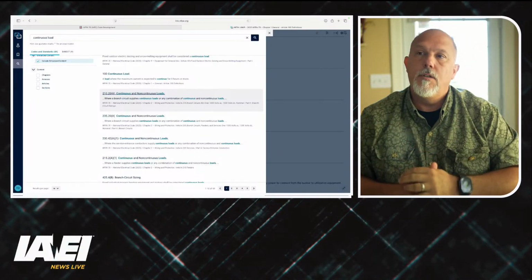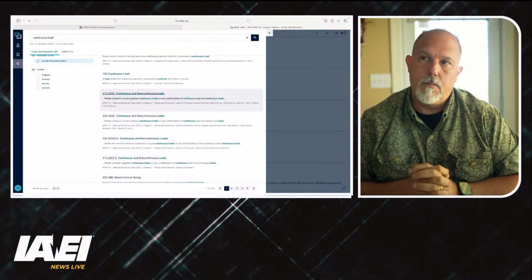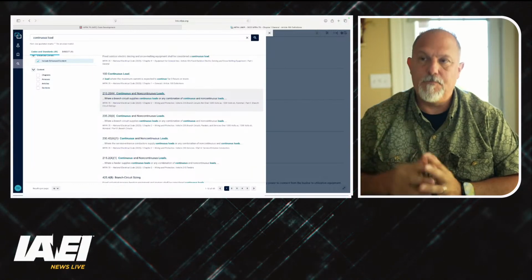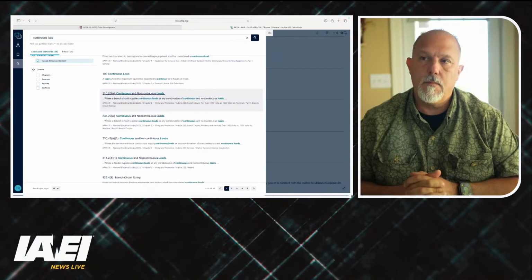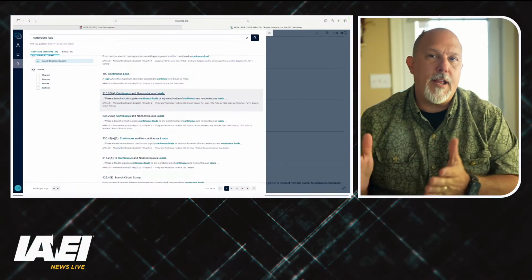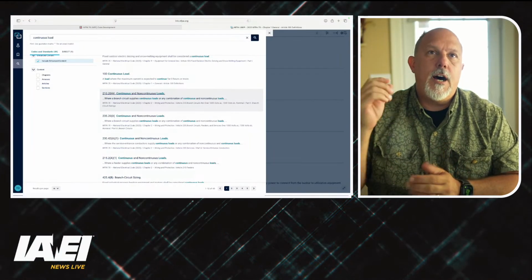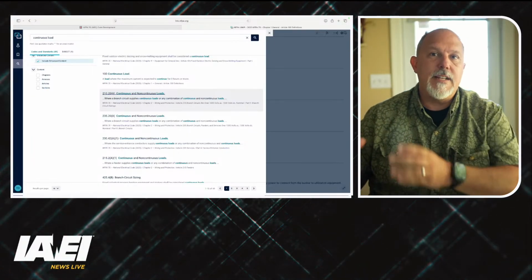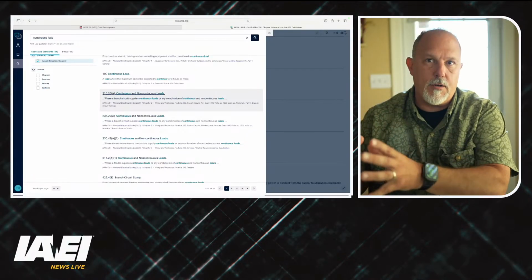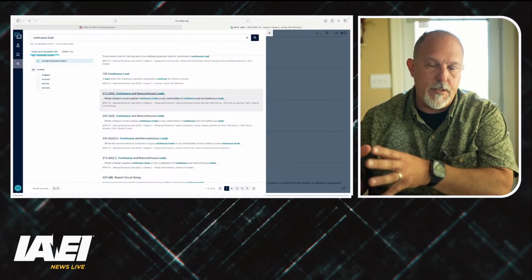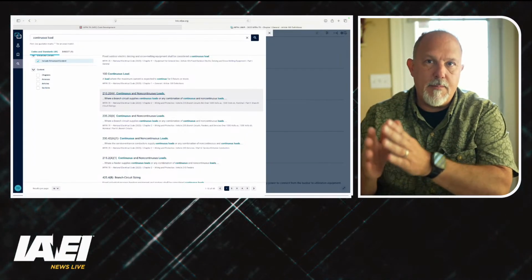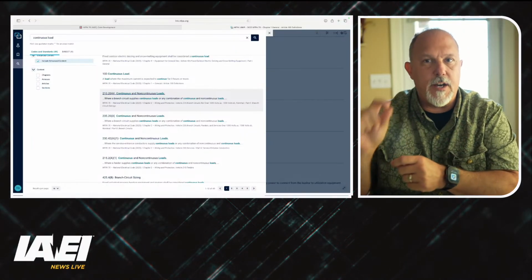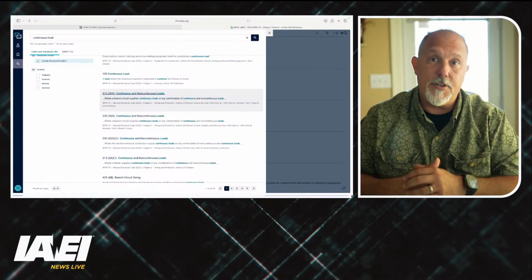Okay? So for example, a 100 amp load. If I take 100 amps times 1.25, I get 125 amps. If I take a 125 amp breaker, which would be adequate, I only have 100 amps, I take 80% of 125, and that's 100 amps.